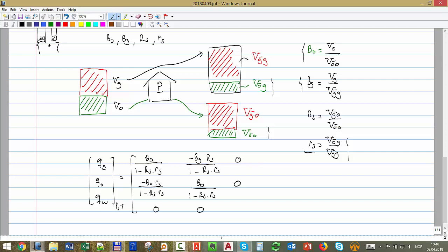Okay, we are assuming that there is no water absorbed by the gas or any water in the oil. Then that will be at a certain P and T, times the matrix; this will be gas, this will be oil, and this will be water. Just that transformation. So what you have to do is compute that matrix for any given pressure and temperature. That you do by calculating these black oil properties, and then you transform.